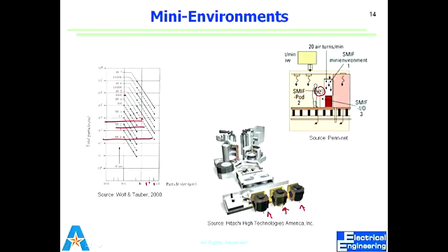So should we leave something to restrict those holes? If you do that, I'm basically breaking the laminar flow inside the hood. If I do that, the vapors are going to come to me because I'm not letting the airflow in a continuous flow. So you see those things, and you have to be careful. You have to use common sense whether this should be done or not.